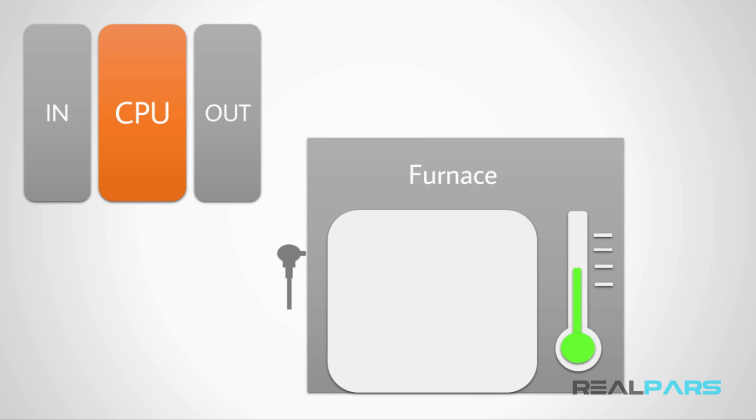For instance, we assume that the temperature range of the thermocouple that we have here is from 0 to 1800 degrees Fahrenheit, meaning that it can measure the temperature of the furnace for us between 0 and 1800 degrees Fahrenheit. So after the thermocouple measures the furnace's temperature for us, it has to transfer this measured temperature to the PLC through a signal. Now, what kind of PLC module can receive this signal from the thermocouple? A digital input module or an analog input module?